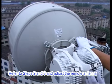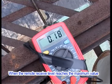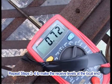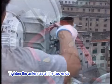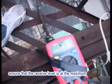4. Refer to steps 2 and 3 and adjust the remote antenna. When the remote receive level reaches the maximum value, tighten the remote antenna. Repeat steps 2 to 4 to make the receive levels at the local end and the remote end reach the planned value. Tighten the antennas at the two ends. During the tightening, ensure that the receive level is at the maximum.